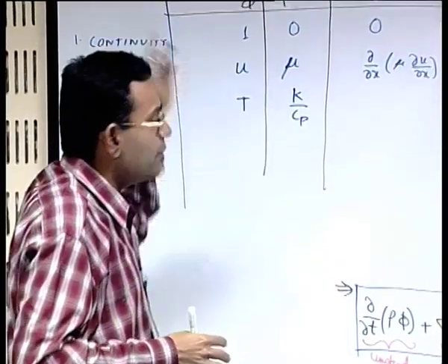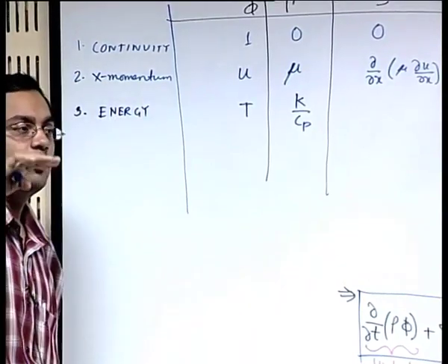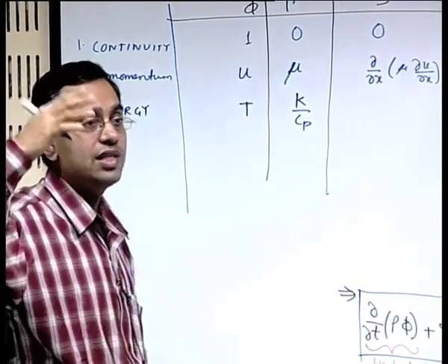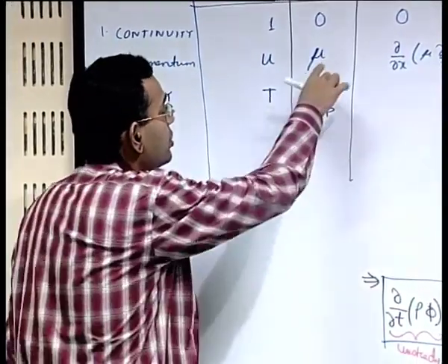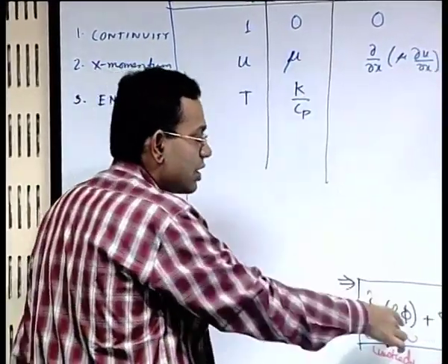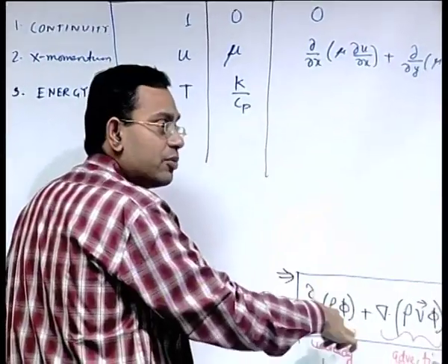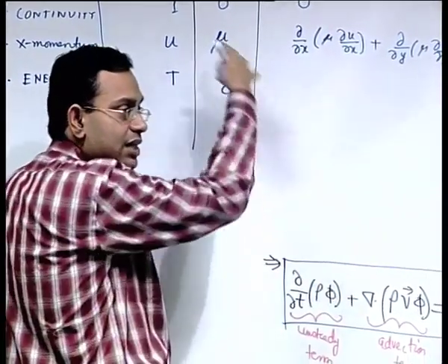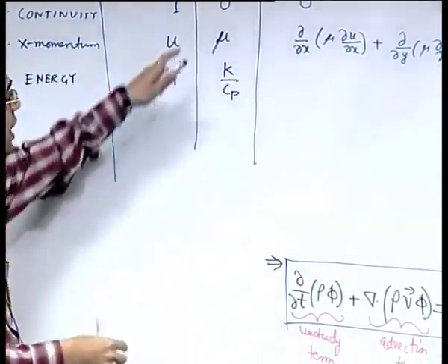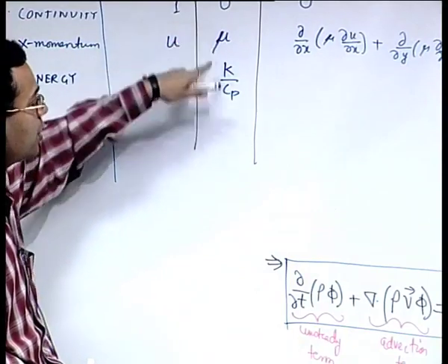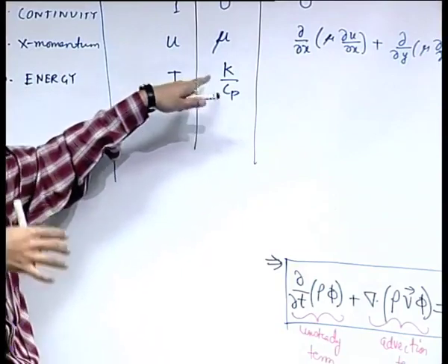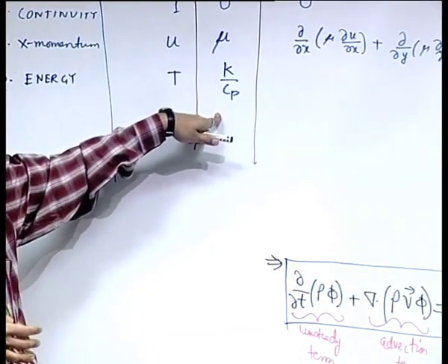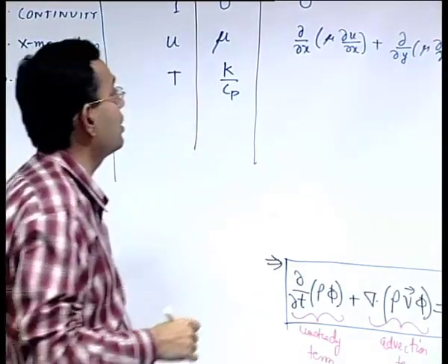For momentum transport it is important in terms of the viscous effect, for heat transport it is in terms of the conducting effect. So here also it could have been mu by rho, but because it is a conservative form the rho is clubbed within the equation, so that is why it has not appeared. Physically the important parameter is this by rho, here also this by rho, because rho is retained within the derivatives, that is how they do not mathematically appear, but physically they are very important.